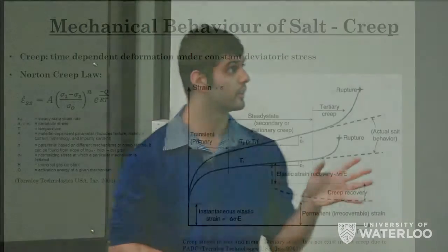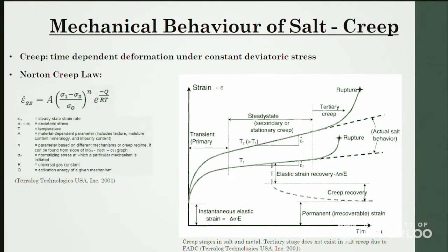So before I move on to the next section, which is numerical modeling, I have one slide on the constitutive equation of salt. Mohammed has already described creep. For beginners, creep is just time-dependent deformation of rock salt under constant deviatoric stress. And there are many equations to model creep, and this is one of them. This is Norton's creep law. Mohammed has described these parameters in his presentation.